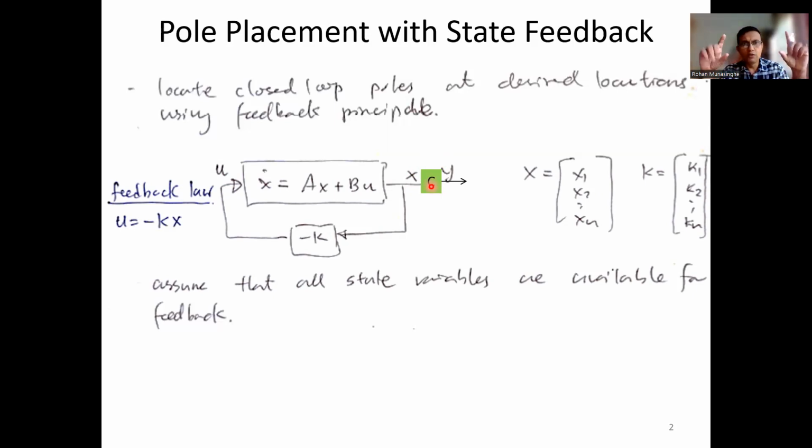In the state space model, you have two equations. The first one is the system equation. The other one is the output equation. The first one goes like x dot equals Ax plus Bu. The second one goes like y equals Cx. All right, so C is the output matrix. And the second equation has another term to make it more complete, plus Du.